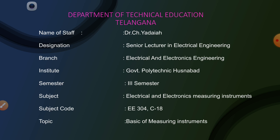To restore, to control, to oppose the deflection torque. If deflection torque is produced by itself, it will overshoot the pointer, sometimes exceeding the full scale deflection also. And when there is no input, the pointer has to come to the zero position, that is, restore the pointer to the zero position for the next operation. For that purpose we require the controlling torque. Without controlling, a pointer will move indefinitely, and hence controlling torque is required.